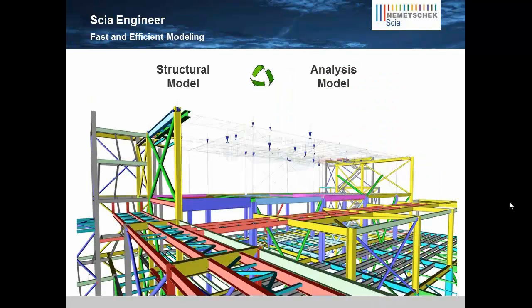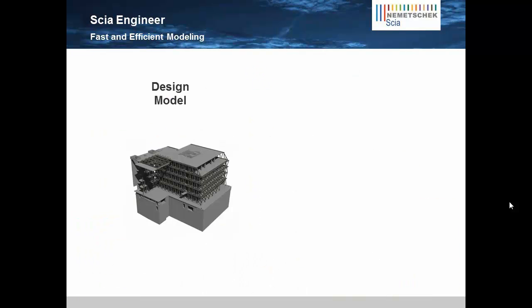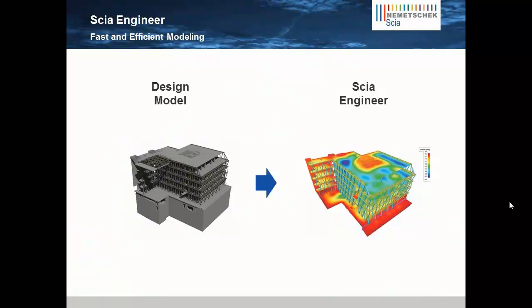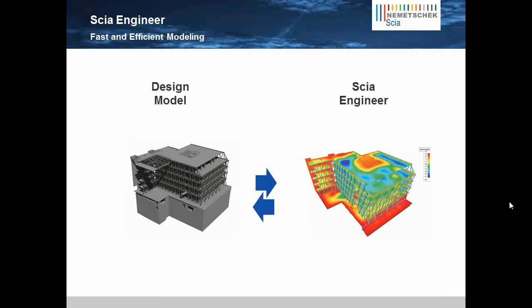In addition, like Revit and Tekla, Scia Engineer can maintain a structural and analytical model in parallel, but unlike Revit and Tekla, Scia can run analysis in the same modeling environment. This offers some great advantages for engineers working in 3D. With Scia, we can start a project by importing a design model and then quickly deriving from it an analysis model, check the model, and then push back an optimized design for model coordination or documentation.